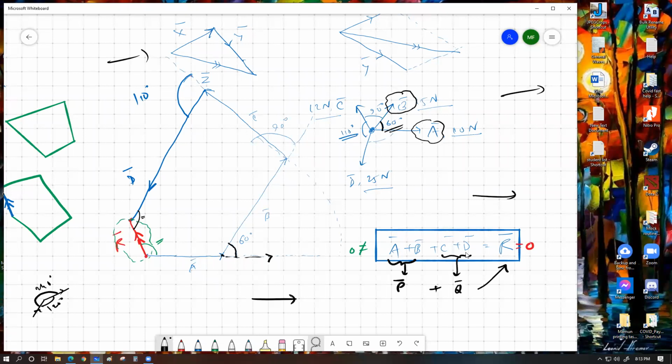So you can take two of the available forces of the polygon one at a time and use the triangle rule for those two, and then solve it for every pair, and then join the pairwise results, and eventually you could get to the same result. The polygon rule basically saves you all the trouble of individual triangle rules and gives you the whole outcome in a single process. If you have more than two vectors involved, we prefer to use the polygon rule because that usually lessens our effort.